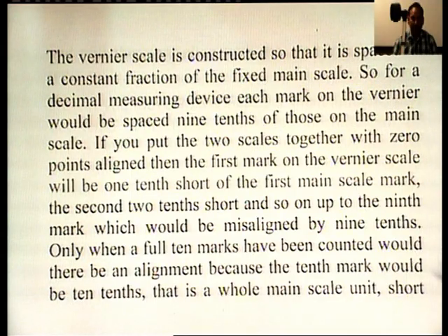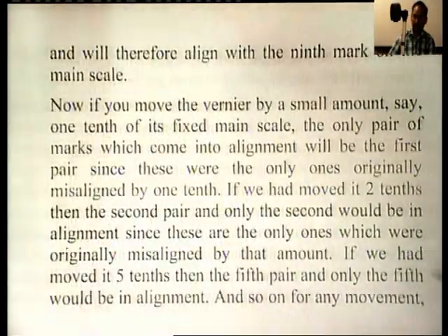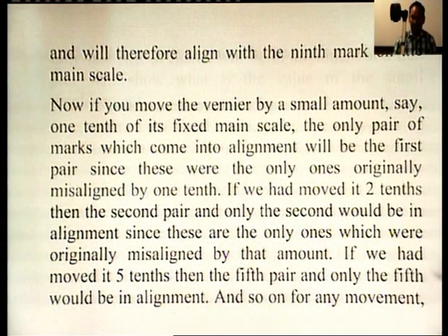Only when a full 10 marks have been counted would there be an alignment, because the 10th mark would be 10/10, that is a whole main scale unit short, and will therefore align with the ninth mark on the main scale.